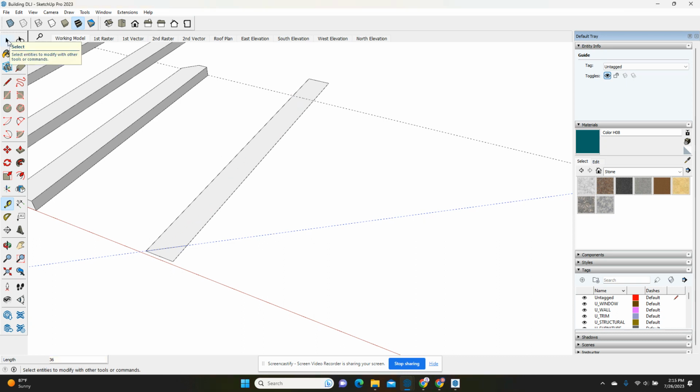I want you then to go to your selection tool, pick on that line right there. If you have trouble and the guideline starts selecting, you can click on the guideline, hit delete and erase the guideline to get it out of your way. Select that line, and while it's selected, go to Move. Pick this endpoint right here. Move in this direction and hit Control one time. And then pick that intersection right there. I just copied that angled line 54 degrees to that location.